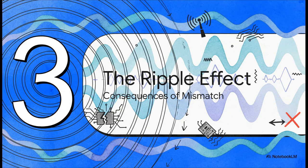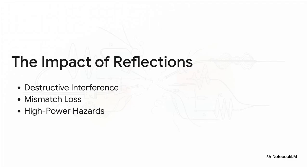Okay, so we have reflections causing standing waves, which we measure with VSWR, but so what? Why does this actually matter? What are the real, tangible consequences of a high VSWR? Oh, it matters. The consequences are pretty significant, actually. Those reflected waves cause destructive interference, which just messes up your signal. You get a direct loss of energy that we call mismatch loss. And if you're working with high-power systems, all that reflected energy can actually travel back and physically damage your transmitter.